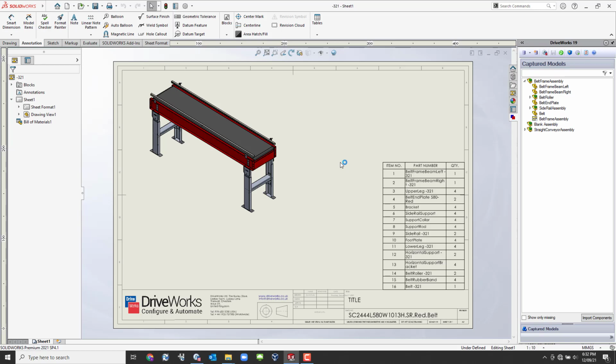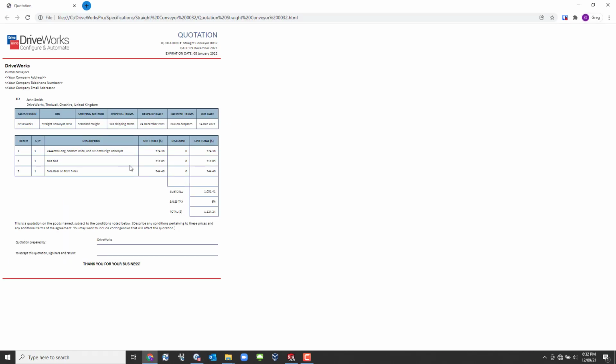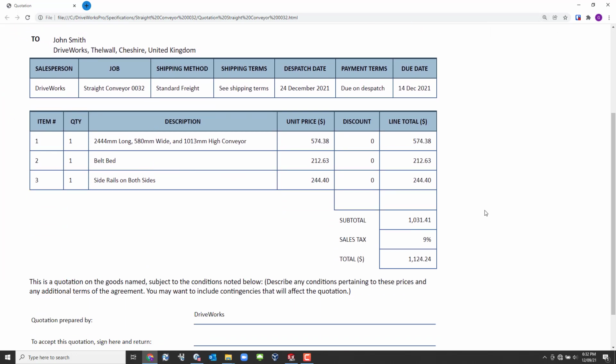So you see, as I've been talking here, I've been through and built the conveyor that I button click through and select, but it takes substantially longer, right? It's going into the CAD model, literally opening it up in RAM, changing the length of this thing, spitting it back out, and then dumping it off to a 244 millimeter long, 580 millimeter wide conveyor system, right? That prior to this took either a ton of equations or an engineer to go and do a save as, open this thing, modify it, hope there was no in-context relationships to be broken during the save as operation, right? And then make a new drawing set out of this thing, right? And with DriveWorks, you just basically strip all that out and leave this thing a skeleton model as it goes and does its job.